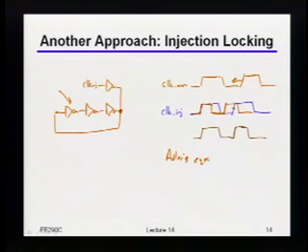Yeah. So isn't the duty cycle set by the delay of the inverters? The duty cycle. What do you mean the duty cycle? To rise and fall, it's roughly about three stage delays. Uh-huh. But if you inject to another frequency, the delay itself won't change, right? Yeah, okay. Maybe what you're asking is, well, hey, wait a minute, you only injected into one point, so isn't that going to cause some asymmetry? You're absolutely right. If I just injected into one point, it would indeed cause asymmetry.